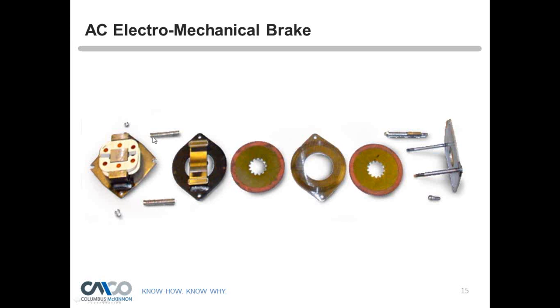The spring pressure is sized by torque, and the engineer sized the appropriate torque. So you never want to substitute springs or think any spring would work. They are designed to have a specific torque and hold that load. So you never want to vary from what the manufacturer supplies. And each brake is different depending on the horsepower of the motor of each hoist. Each brake is designed for the horsepower of that motor.